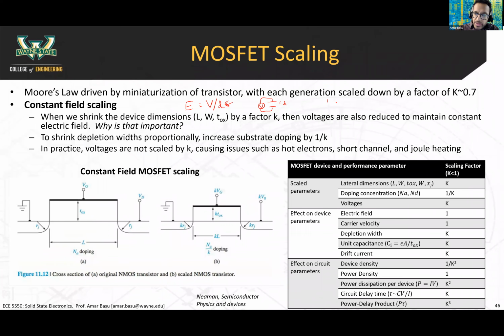Now, this will make most sense to some of the electrical engineers in the room, but this is a basic RC circuit. You have a resistance, and then you have a capacitance. This is a type of circuit that happens when you have a transistor that looks like this, and you have another transistor driving the gate of that transistor.